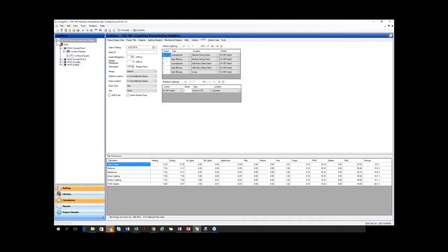So coming back now to the HERS tab, we showed you how indoor lighting is affected. The other change is with appliances. So here you input appliances for your refrigerator, your dishwasher, and one thing with the dishwashers is you are required to input a dishwasher. In non-residential software, you won't be required to do that. And same with the washers and the dryers.